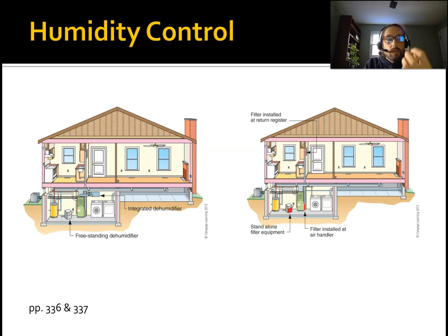But what they do is they just basically pull moisture from the air, and then you deposit it in a little basin. You can also use modern air conditioners; modern heat pumps will have settings where you can dehumidify the air. So remember, in order to dehumidify the air, you have to drop it below the dew point. Okay, and so there's sort of programming where you can run your air conditioner on sort of a real low level, even if you don't really need the cooling.